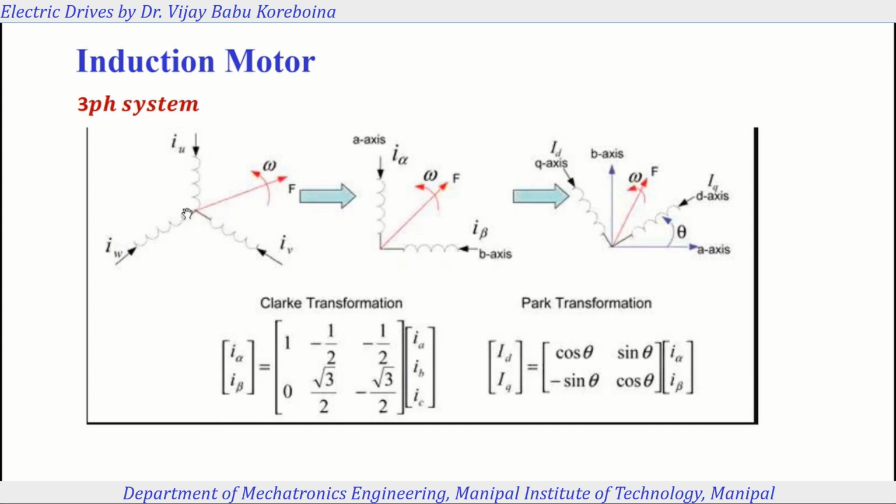It is a simple mathematical graphical analysis. We take one of the axes along with one of the phases, and the rest are transferred onto the quadrature one as well as onto this one. The components are dropped onto that axis. For example, it's 120 degrees, which is nothing but 30 degrees, so 90 plus 30 is 120.